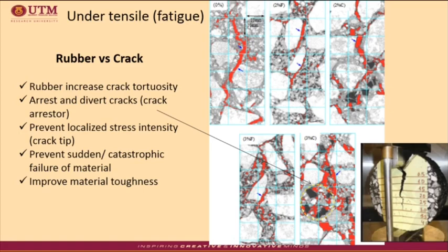For the control mixture, the main cracks are shown to have propagated through the binder and fines, whereas for rubberized mixtures, the rubber particles appear to have added resistance to crack growth. At the onset of catastrophic failure, when the cracks meet the rubber particles, crack tortuosity is increased through the allowance of greater elastic deformation, particularly near the crack tip,